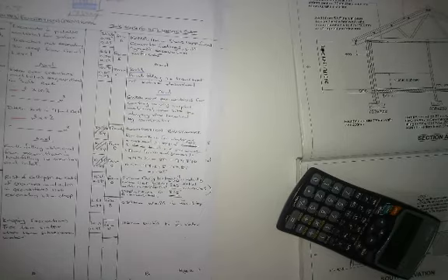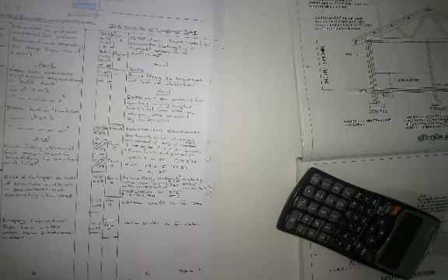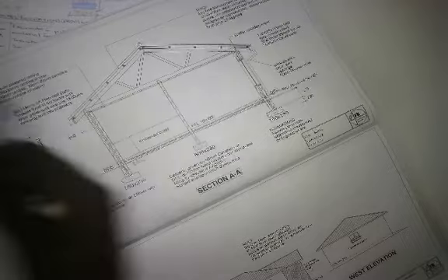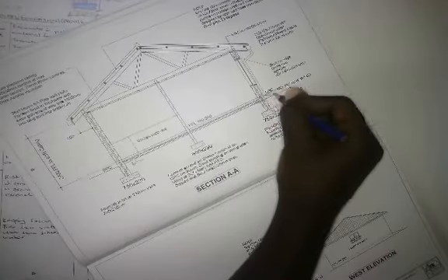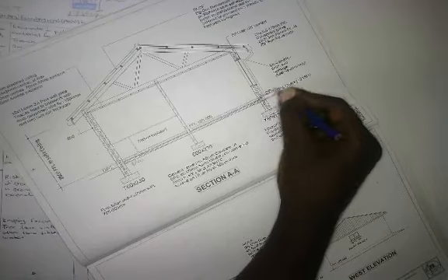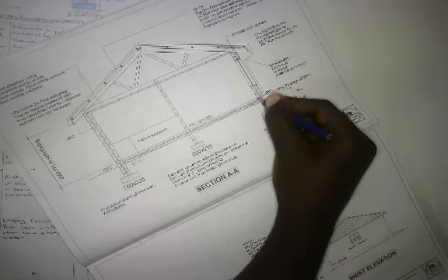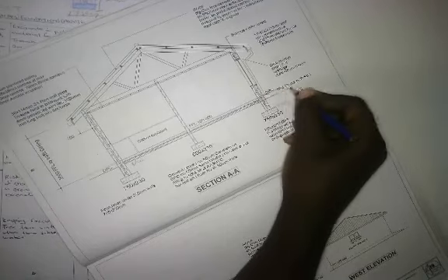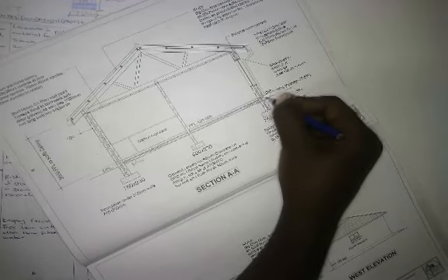Just take from each type of wall type and put the concrete according to its specification. That's fine. And then we go to foundation brickwork. Okay, so it's a 270 cavity wall in foundation brickwork. Now what we usually say, as per the norm in industry, is that our foundation wall usually ends at DPC level.